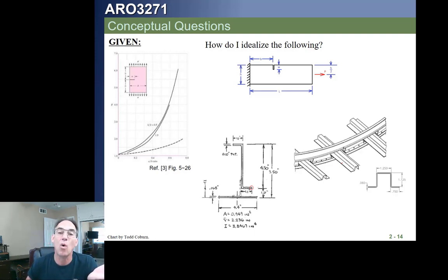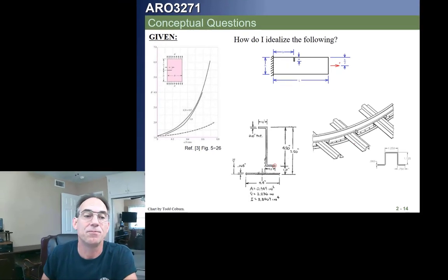Or we can assume that the whole part is effective, in which case we'd take 0.75 minus 0.03 plus 1.125 plus 1.25 minus 0.03 minus 0.03 plus 1.125 plus 0.75 minus 0.03. If we assume that's the total length, plug that in as our B, that would be appropriate for an axial kind of load. So make sure you practice that, study it out.